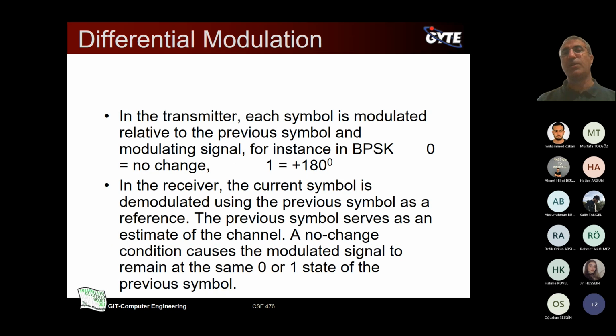That's the basic modulation. We have a different modulation technique, and one of them is called differential modulation. So far we talked about basic modulation, which is conventional modulation, where you modulate each bit or group of bits one by one. It doesn't depend on any previous or next symbols or bits.